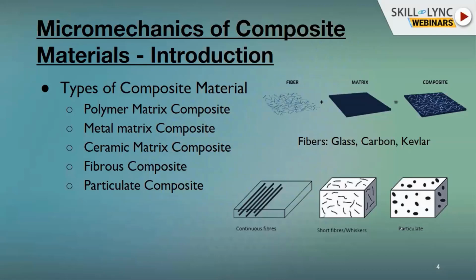So they form the basic fiber layers, and then a bonding layer of epoxy. In the case of polymer matrix, we will have epoxy as a matrix material. So they are used to form the composite material at a very basic level. We call it a lamina. Each lamina is formed in different segments, and they are stacked layer by layer to form a laminate. Based on the design requirement, the number of layers defines the thickness of the composite.